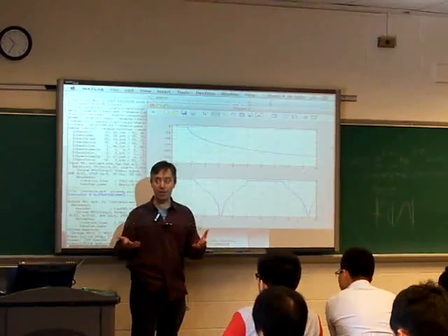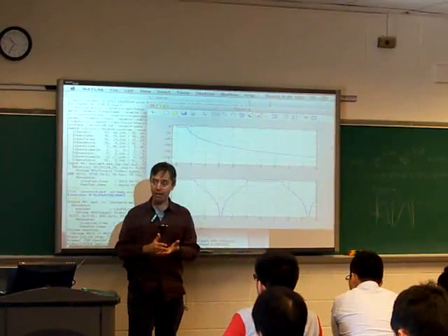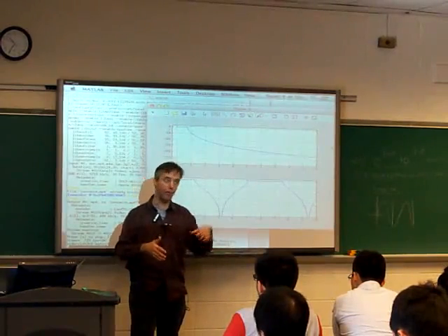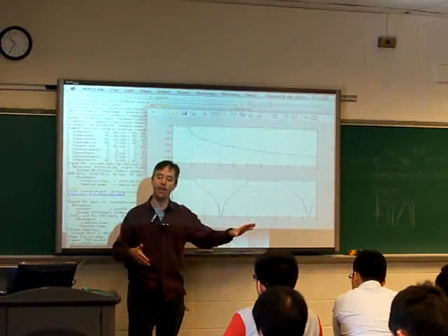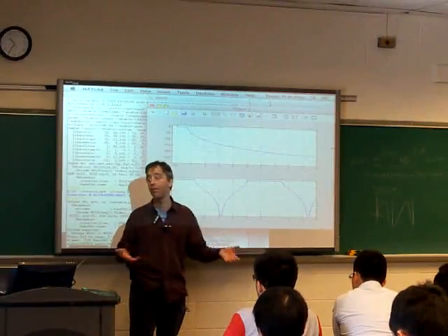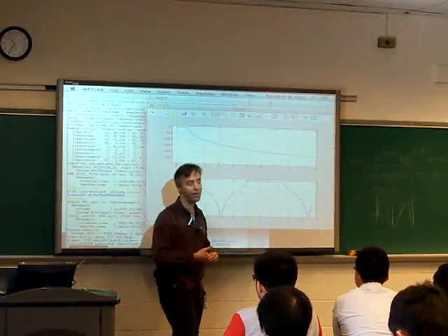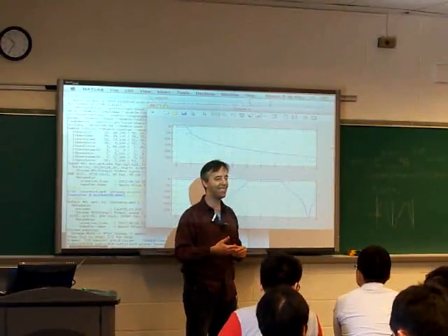And at the same time, when we actually do the sampling, when we run our A to D, we have to make sure that we've already eliminated any energy above that Nyquist rate from the analog signal. Otherwise, it's going to cause aliasing. That's what happens. So are we okay?